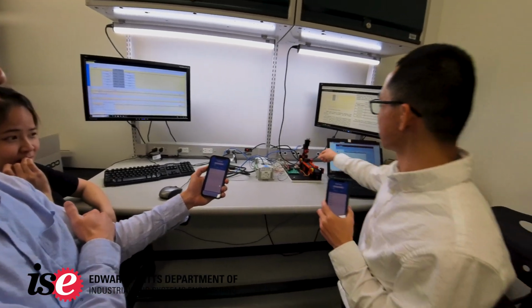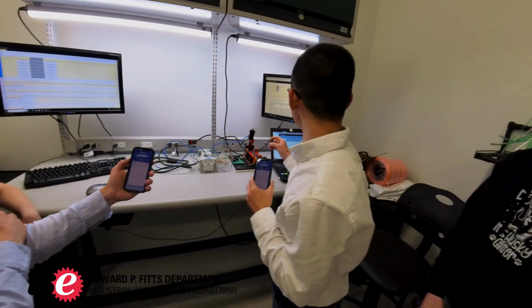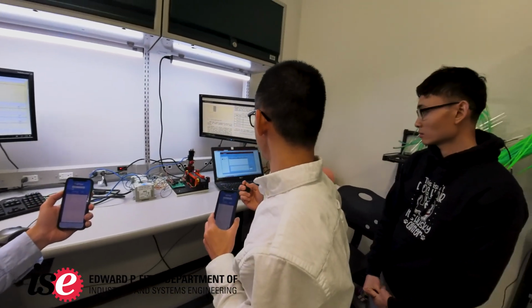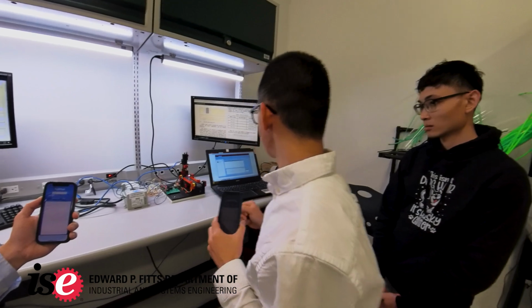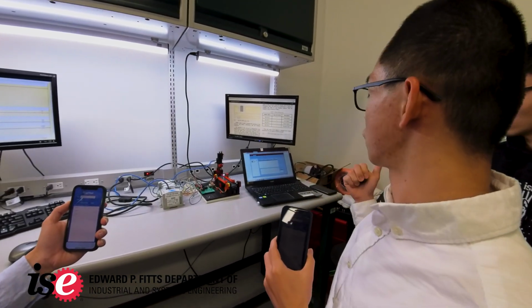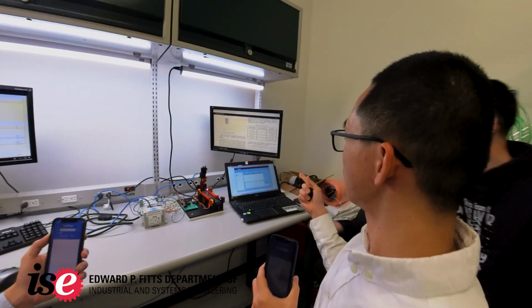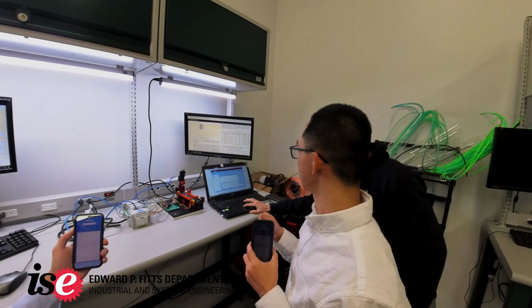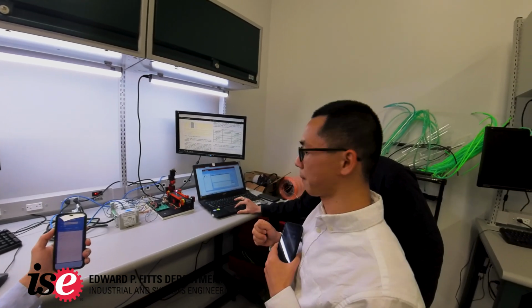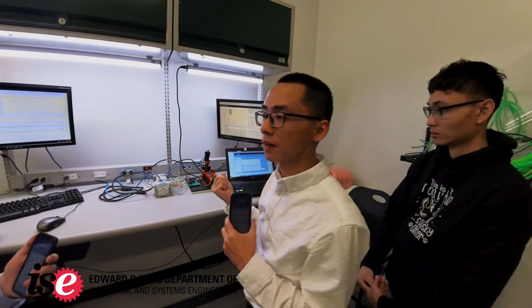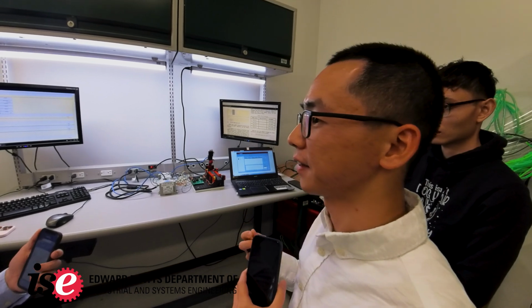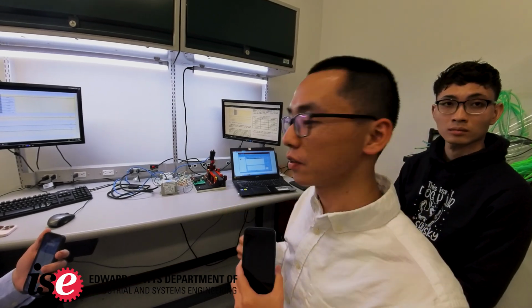And we can try the emergency stop. So when the conveyor belt is running, we can change the address 3 to 1 to stop the conveyor. Yeah, and the conveyor will stop, and it means that our emergency button is working, and that's our demonstration.